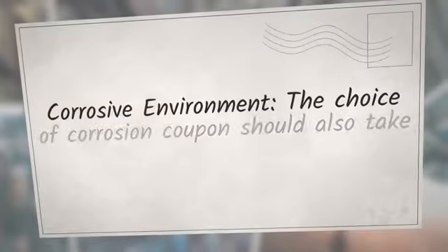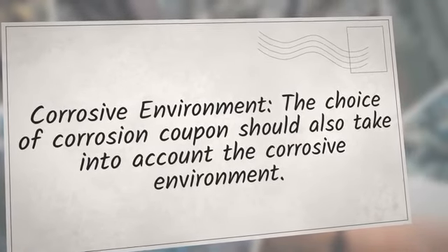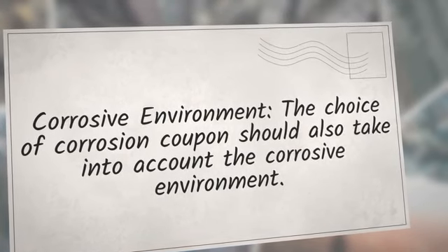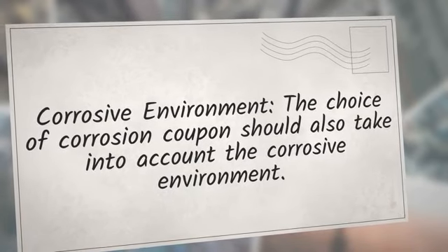Corrosive environment. The choice of corrosion coupon should also take into account the corrosive environment. For example, coupons exposed to highly acidic or alkaline environments may need to be made from a different material or coated with a protective layer.